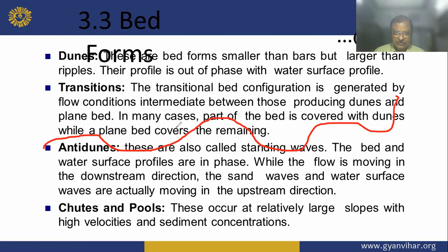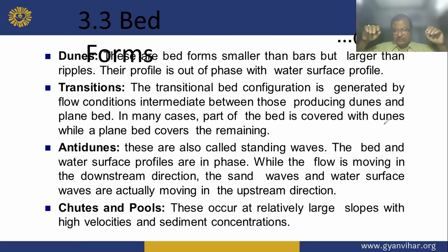This is webs. The bed and the water surface profile are in phase. While the flow is moving in the downstream direction, the sand wave and water surface wave are actually moving in the upstream direction.